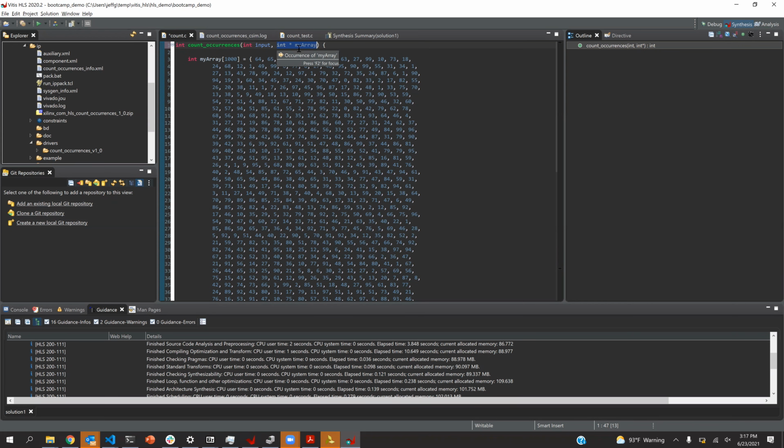If you take 427, what we always do in 427 is we make Space Invaders running on the pink board that I had here last time. Generally it's out over HDMI. There's a buffer in memory that controls what's drawn on the screen. Generally drawing stuff on the screen is pretty slow because the processor says, oh, go to this address, draw a red pixel. Now go to this address, draw a black pixel, and it's all going through the processor.